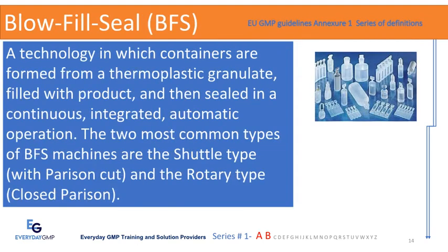Blow Fill Seal, BFS: a technology in which containers are formed from a thermoplastic granulate, filled with product, and then sealed in a continuous, integrated, automatic operation. The two most common types of BFS machines are the shuttle type, with parison cut, and the rotary type, closed parison.